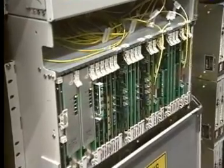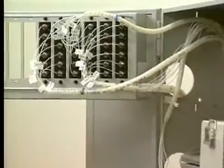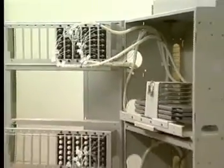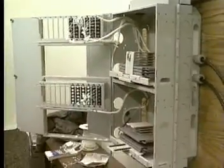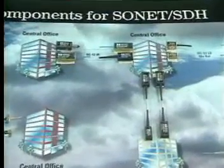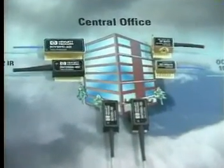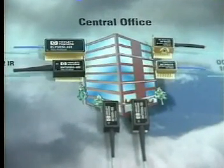When used in fiber-rich systems, source bandwidths can be slower because more fibers can be used to carry the signal load. Thus, lower speed lasers or even LEDs could be used. However, in high-speed multiplex systems such as SONET, high bit rates make lasers the only choice.